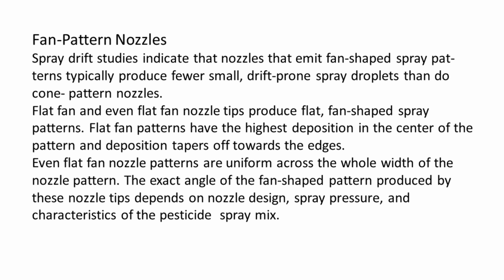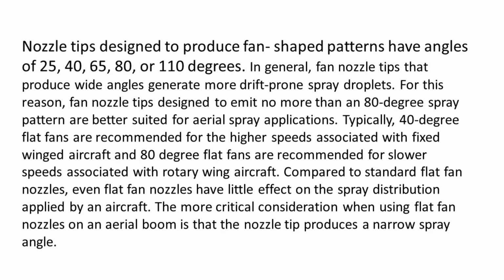The exact angle of the fan-shaped pattern produced by these nozzle tips depends on nozzle design, spray pressure, and characteristics of the pesticide spray mix. Nozzle tips designated to produce fan-shaped patterns have angles of 25, 40, 65, 80, or 110 degrees. In general, fan nozzle tips that produce wide angles generate more drift-prone spray droplets. For this reason, fan nozzle tips designed to emit no more than an 80-degree spray pattern are better suited for aerial